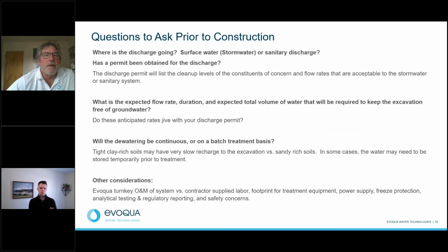In Jeff's case, they used well points, and the water coming at us then is pretty clean. It's just like coming out of your water well at your house, if the screen is sized to the soil type that's in there. So once you get it developed, the water coming out of the ground is essentially free of solids. But if you've got an open excavation, like the one we had along the Platte River, full of silt and clays, it's a whole different treatment train to deal with those suspended solids.